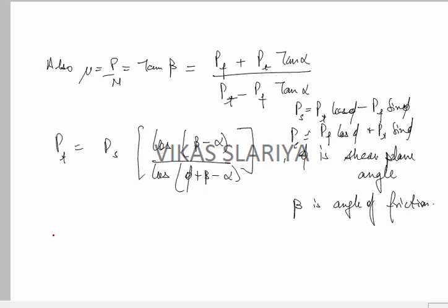It is also to be mentioned that PF and PT are vertical and horizontal force components. So this is the result for my tangential component, which is coming finally, or the force responsible for cutting.